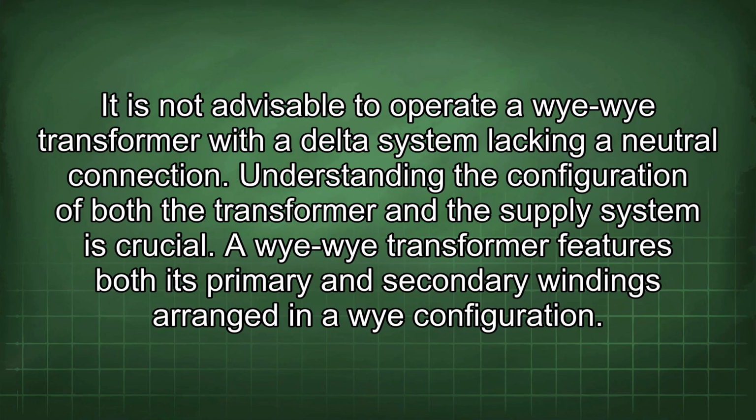It is not advisable to operate a Wye-Wye transformer with a delta system lacking a neutral connection. Understanding the configuration of both the transformer and the supply system is crucial. A Wye-Wye transformer features both its primary and secondary windings arranged in a Y configuration.